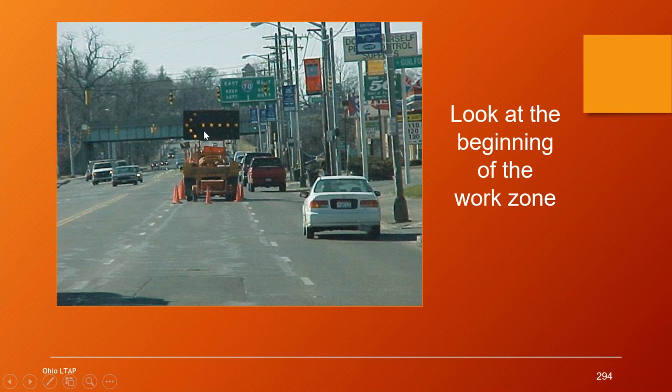That's why even though this arrow is telling them to get over here, these guys are thinking, well, I'm not getting over there because I got to get on the on-ramp here. So this arrow board should have been a two-headed arrow. Let's try it this way, like that. So that way the motorists know that they have a choice on going around them to the left or to the right.